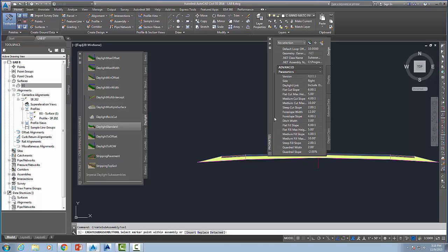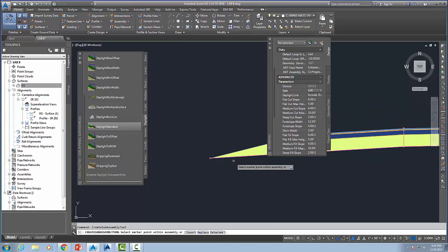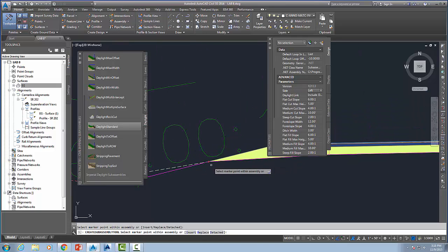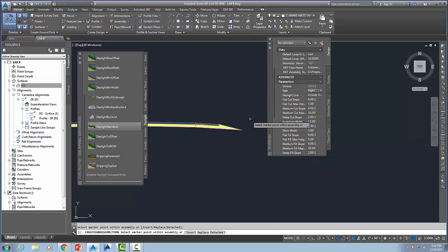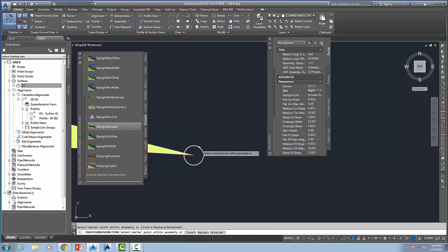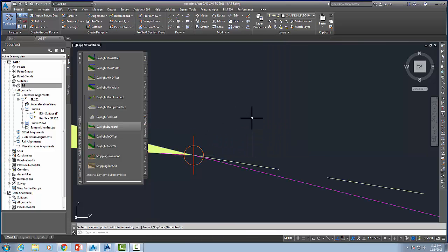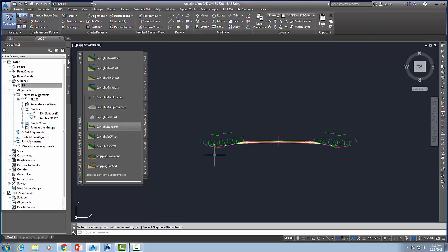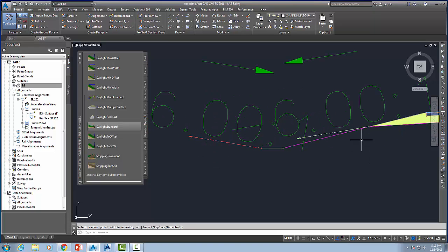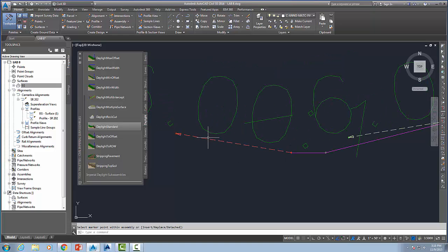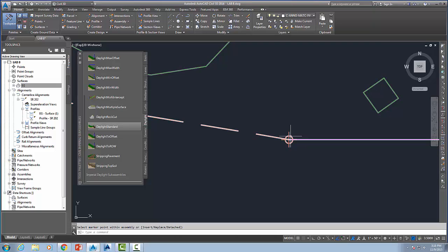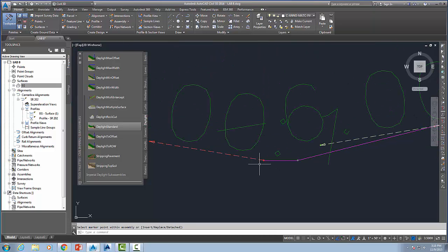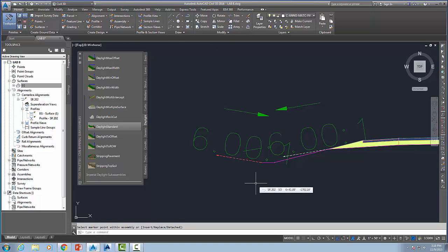So we're set to right. Again, I'm going to go ahead and go to left. I'm going to attach that to this point right here, and I'm going to do the same thing on the right. Attach that over here. And I've got it. So that's what we're going to be dealing with. Now here are your 4 slopes, there's your ditch section, and this is your actual daylight line. So this point right here is what we would typically call our hinge point, because it can hinge up or down from that to where the daylight section is going to occur.